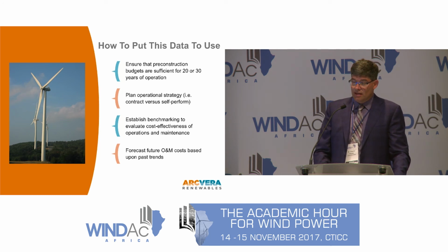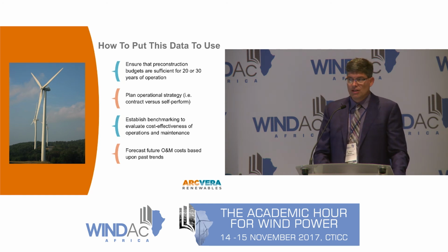Given the fact that turbine financial modeling is going out 25 to 30 years now, ensure that you've considered this type of information as you move towards those longer lifetime estimates. Plan your operational strategy carefully. That is, if you're going to transition to self-performing your O&M after the period where the OEM is doing that work, do so with great care and make sure you hire a top person to oversee that. It's well worth the money and salary to do so for the long-term performance of your wind farm.